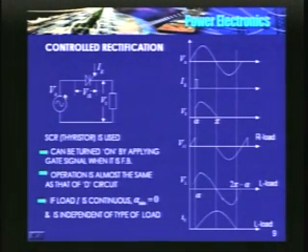Okay. So when the device is on, circuit behavior is the same as that of the diode circuit. That is almost the same, there is not much difference. But there could be some difference in the waveforms, we will see. So in the positive half, I am assuming the load to be passive. Somewhere in between 0 to pi I am triggering, alpha is the trigger angle, finite Ig is flowing, SCR turns on.